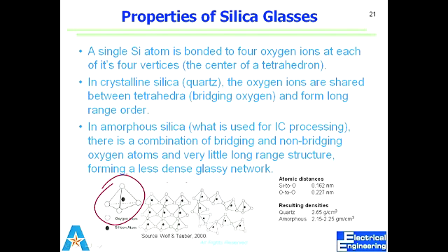Optically, the oxide we grow, is it essentially glass? Like, we could actually oxidize a whole wafer, would it become a wafer of glass? It will be all glass, but it's going to take a few days before you get there. And we could do that. Yeah, not that you would want to, but essentially we'll end up with something which will be a thick glass, telescope glass. And what we can do is we can buy glass wafers directly.